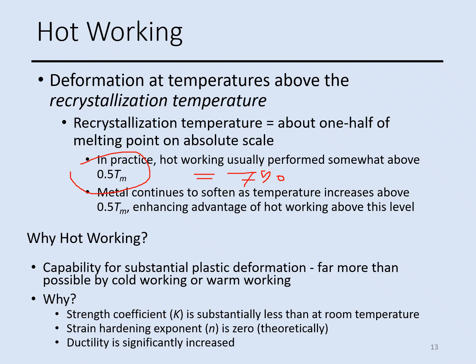So they increase the temperature, so the load for plastic deformation can be reduced, because that value K, as I mentioned before, the strength coefficient, is substantially less than the value for room temperature. And at high temperature, that n number, the exponent, becomes zero, theoretically. And ductility also increases at a hot temperature.